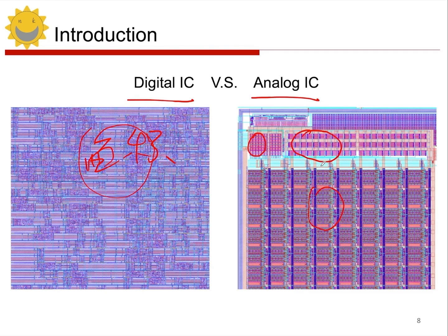It's because when we design the layout for analog circuits, we need to fully consider factors like matching and noise. By taking these factors into account, the structure of the circuit tends to be more organized, which enhances the performance of the analog circuit. To achieve a certain level of matching, we might sacrifice some area, but this sacrifice is necessary to ensure the circuit's performance.